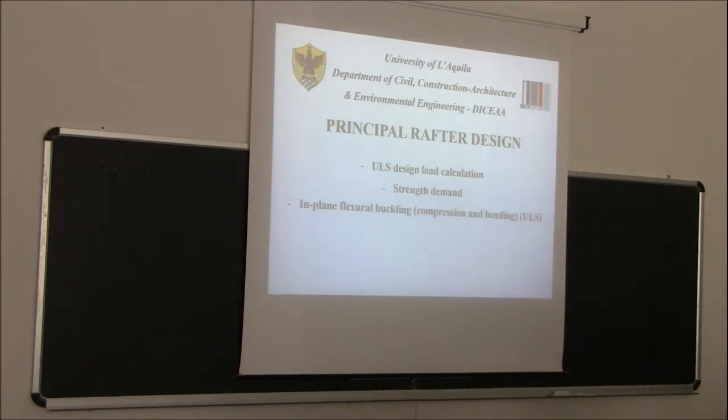So we'll have, in Italian, instabilità a carico di punta. So this member is subjected to compression and bending, in-plane buckling. And then it will be a matter of finding out the problem of out-of-plane buckling. So this may buckle in plane, but can also buckle out of plane. So the out-of-plane buckling will be compression and lateral torsional buckling.